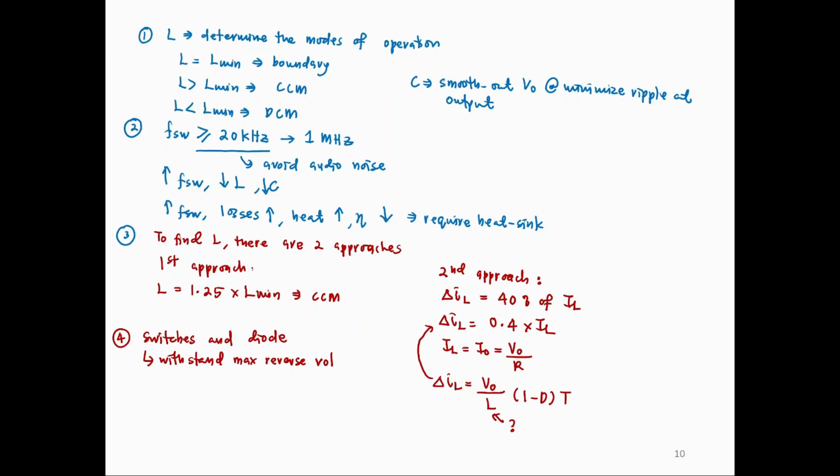So in order to do that, you need to check the switch data sheet and make sure that you select a range that is higher than your output voltage. Let's say your output voltage is 50 volt. Make sure whatever switch you are using, at least the rated voltage is maybe 300 volts or 500 volts, much bigger than the output voltage produced from the converter.